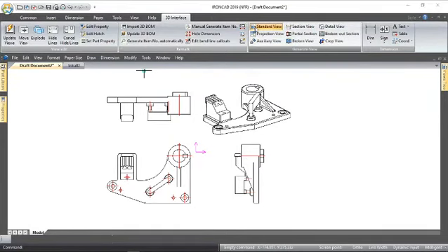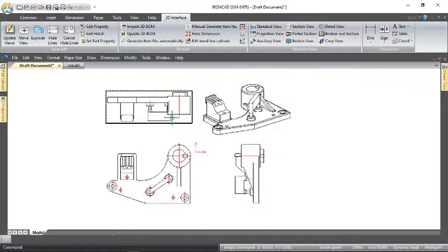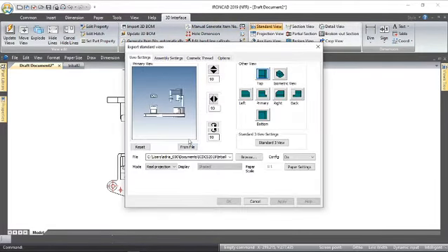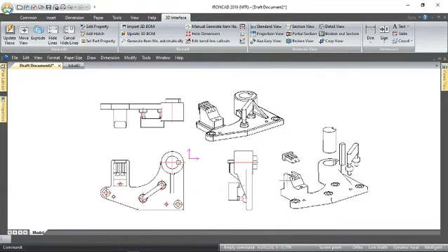And I'm going to go back in here now, go standard view, from file, but this time I'm going to go to in config, and I'm going to select this, and that will show you the exploded version of that model. So let's go back in here, from file, and select this there, and I'll just put that one in there like so and go OK. And now basically I've got another version of that which is showing the exploded model like so.